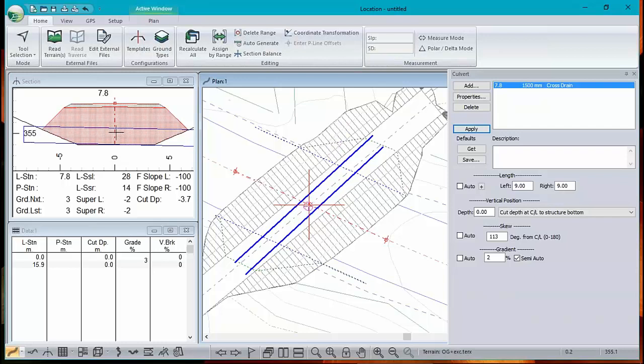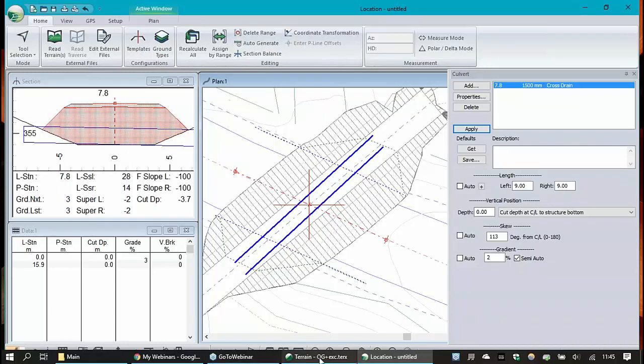We're looking at a projection onto a perpendicular cross section. So it's not an ideal section. You really have to take it to terrain to get a skewed cross section. And you can do that in both version 8 and version 9, but let's take a look at the results from a version 9 export.